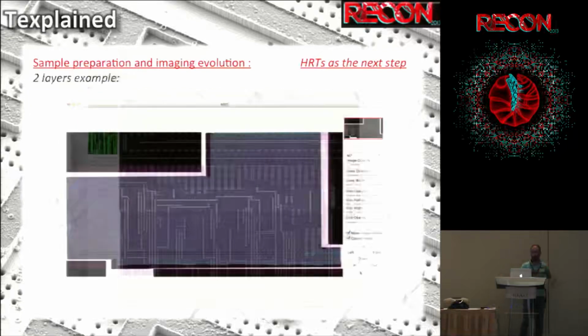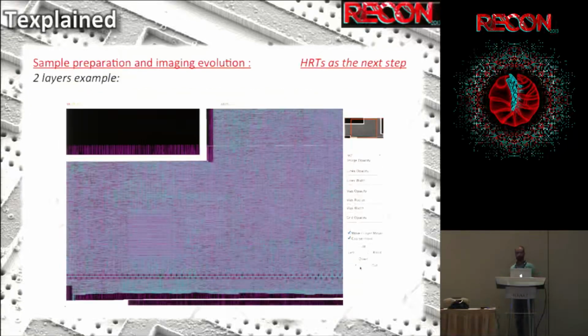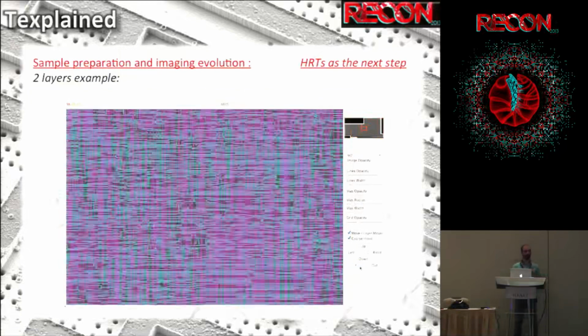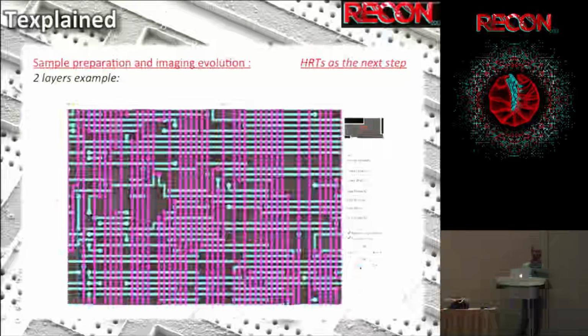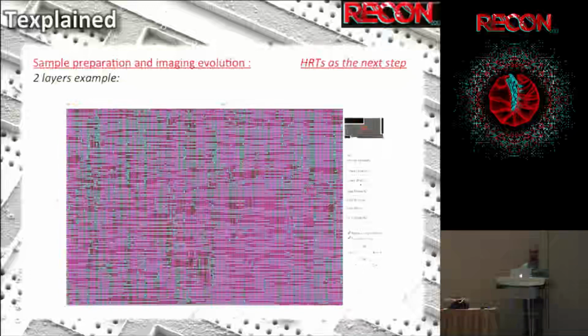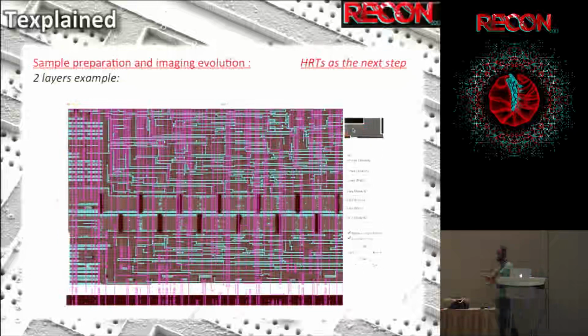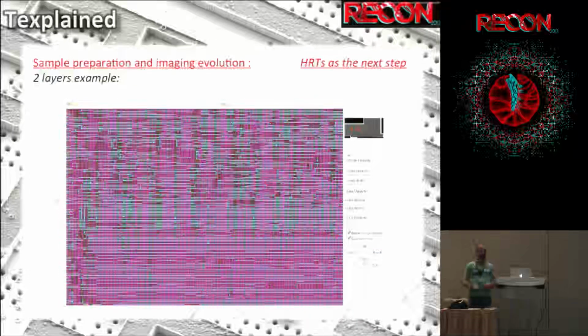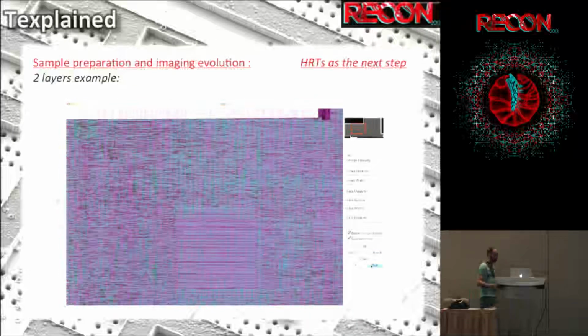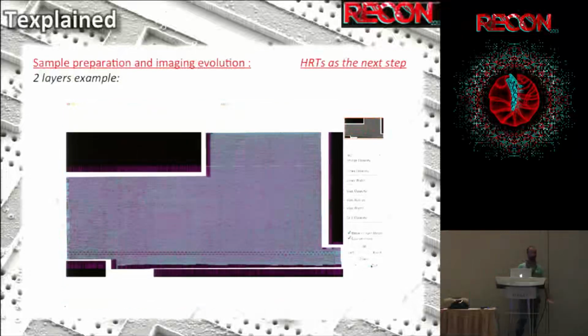And just after that, you have to align 2 layers together. And this is very easy, because now you align 2 layers that are lying on the grid. You have a bonus now, because you have used this principle. You can use a magnification which is very low for the top layer, because the lines are big at this stage. And then you can use a very high resolution for the bottom layer. But when you want to align the 2 layers together, you don't speak about resolution or magnification. It's grids that you align. So it will align perfectly. And you will have no stitching error for 1 layer and no error for the alignment of the layers.